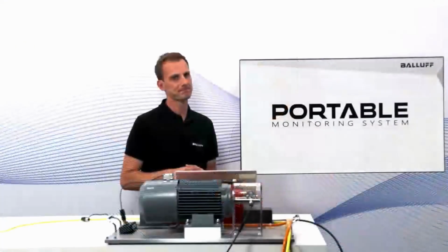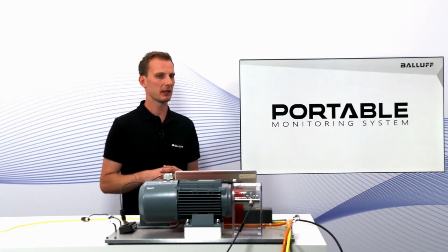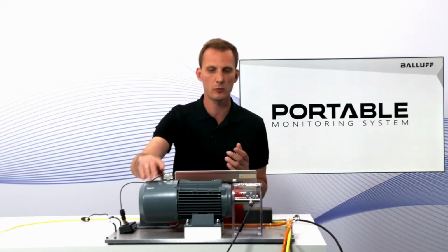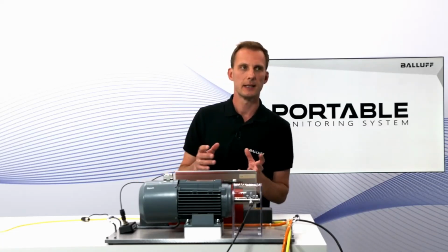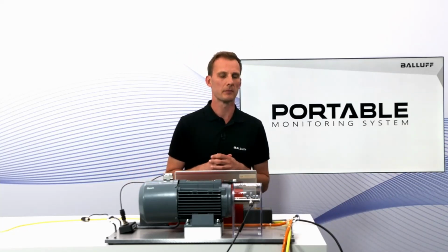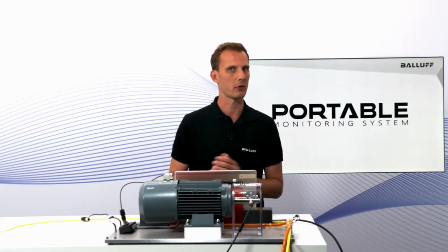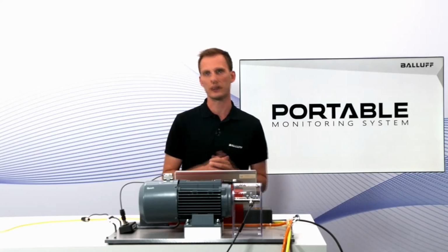Another question that was coming in is, how do you determine the correct position or place for the sensor? To be honest, you probably already know because you know where the vibration is coming from. Is it coming from the head or from the bottom of the motor, or wherever the location is? But if you don't know it, it's basically a little bit of trial and error. But I guess that most experienced maintenance persons who take manual measurements today know where the vibration is coming from and where to place the sensor.